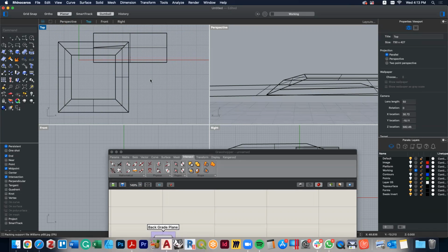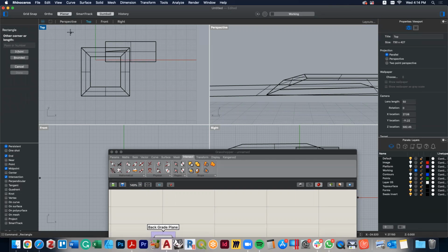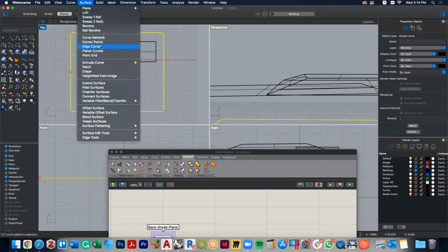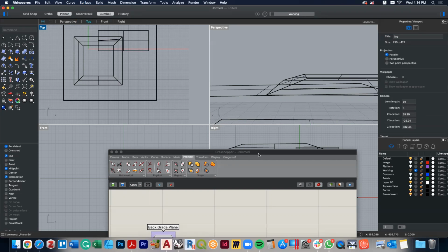And so what I'm going to do now is create another surface, because I'm going to use a command that's called the project command. So I'm creating another surface now, and I'm going to make it a planar curve. It's another surface at the base. It's not a surface that we're going to model from. It's a surface that we're using for another purpose, which is to create what's called a projection. A projection is literally, imagine if you had a three-dimensional object, and imagine I had a data projector that casts a shadow. That would give me a flat version of this three-dimensional thing. So it's called project, and it's so that we get a flat version of that line.